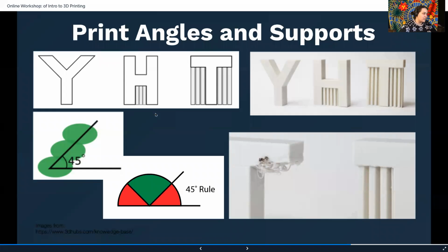And you can actually turn these supports on automatically in the slicing program, and these supports are what you see in Cura. They're just these blocks of filament that they put in a zigzag pattern. It's a lot of filament, and it leaves kind of a rough spot, but it keeps your print from looking like this and completely ruining your part.